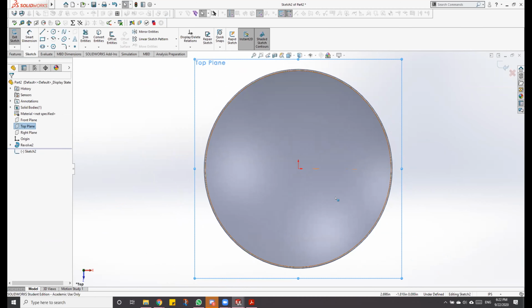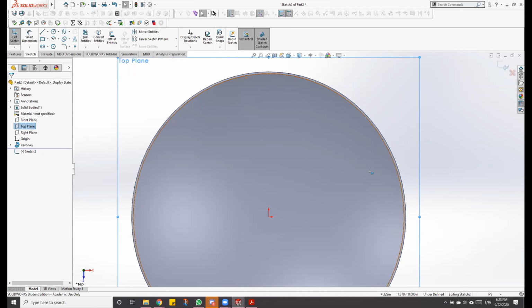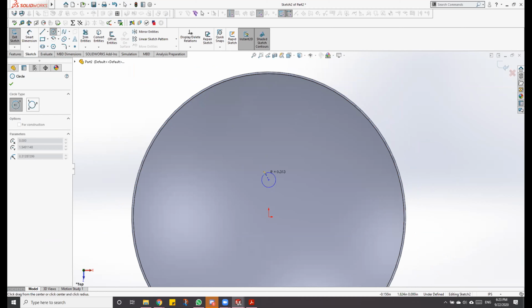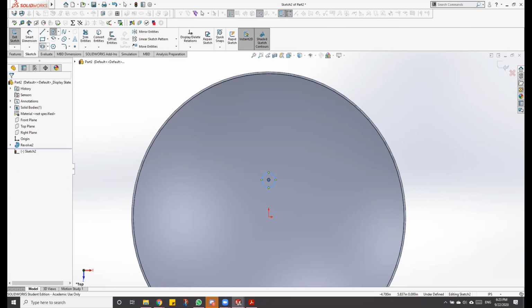So I'm just gonna give you guys freedom to make the holes, but you have to follow these instructions. What we do is make one set of holes going along the vertical, and keep them along the vertical. So I'm gonna make a little hole here, and I'm gonna use the slot feature, which is over here up in the sketch, straight slot.